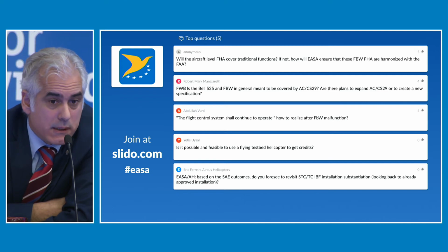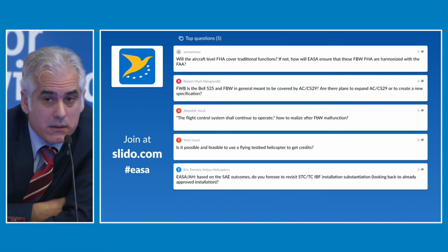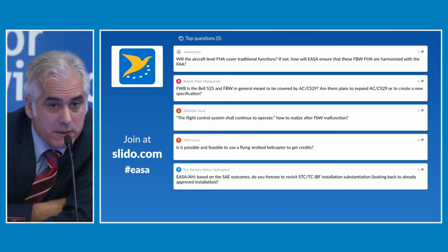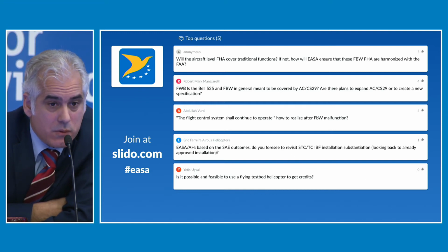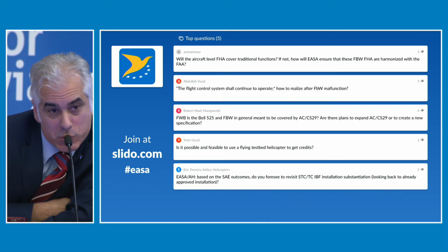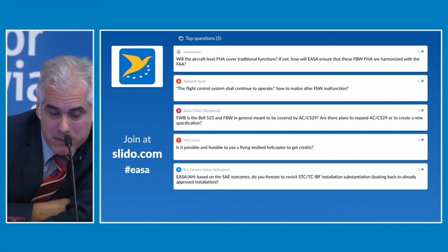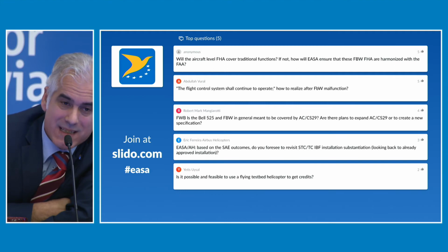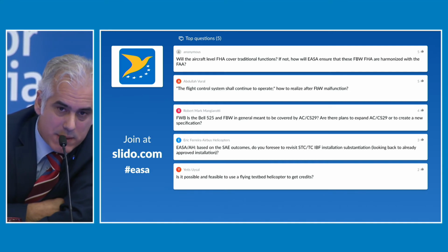If you take a Part 29, let's say a 20,000 pound aircraft being built in Europe and a 15,000 pound aircraft built in the United States, there's no difference on the functional hazard assessment. There is no question what's going to happen when I lose control. We're talking about functional. We're not talking about system safety assessment. Sometimes people do confuse a failure of systems as a prerequisite of a functional hazard assessment.